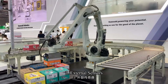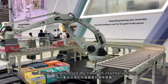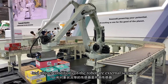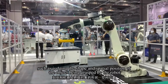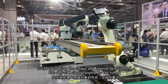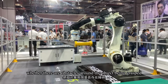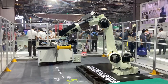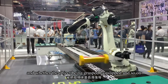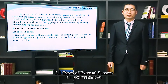3. External sensors. The sensors used to detect the environment and object conditions of the robot are external sensors, such as judging the shape and the spatial position of the object being grasped by the robot, whether there are obstacles around the object being grasped, and whether the object being grasped has slipped, and so on. 3.1 Types of external sensors.